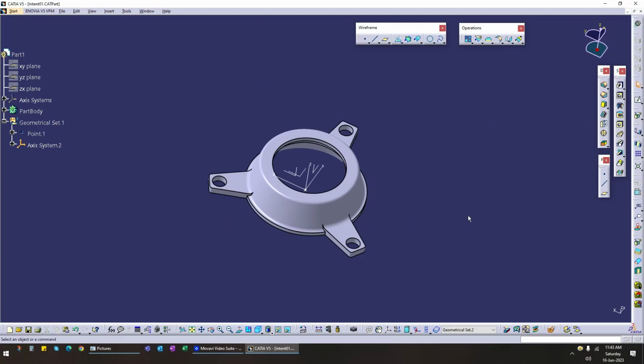In the end, we can conclude that the 3D model that we create must be easy to understand by anyone. The sketch profiles we create must have a single closed profile for the sake of simplicity. We should define relations between features such that any changes to one feature must automatically propagate the change to another related feature.